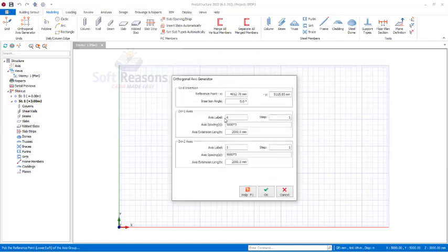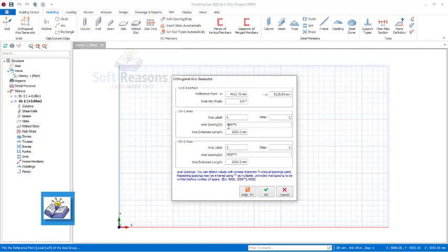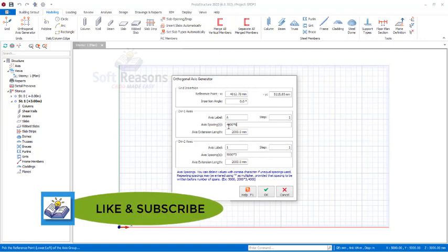At first, direction 1 axis, we are having labeled A. This simply means the horizontal direction. So in the horizontal direction, we will be having a space of 4,800, and then we are going to asterisk it with 6, meaning 4,800 is six spaces in the horizontal direction, while direction 2 is the vertical direction, and then it's being labeled